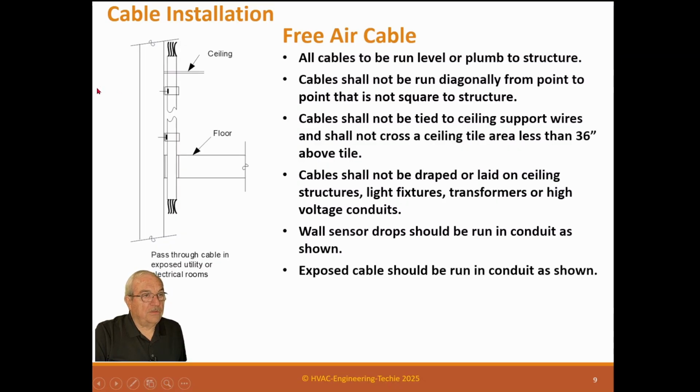Exposed cable should be run in conduit as shown. So in other words, let's say you've got a vertical rise going up a building and it runs through a mechanical room or electrical room. So down here you have your free air cable and up here your free air cable, but this is an exposed area.